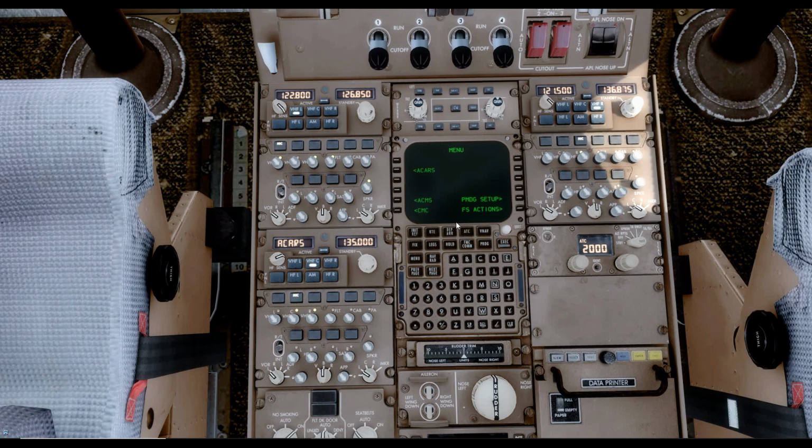And then finally the transponder panel. We haven't had our clearance from air traffic yet, so the transponder's in standby. 2000 is set. We'll get our code from air traffic in a moment, and the transponder selector is usually selected to the side that the pilot flying is sitting on. We're flying from the left hand seat today, so we'll use the left function. So that's it, that's the panel scan done really.